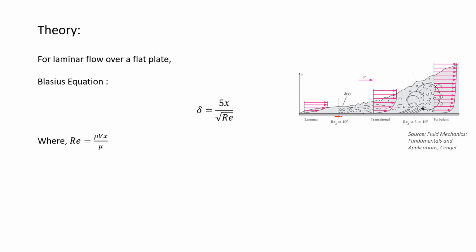But inside the boundary layer the velocity increases as you go up. So close to the plate, there will be a no slip condition, which means that just adjacent to the plate the velocity will be zero, and slowly you see this vector increasing. So it was here, it was here, and then it was here. So this kind of profile is there.